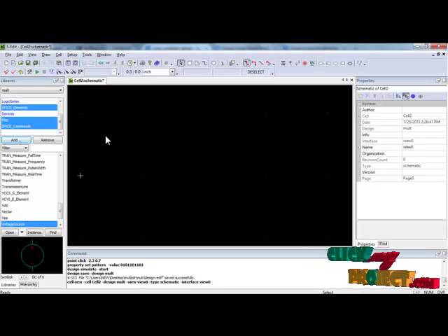After we design in S-Edit, while simulating, the circuit design passes through T-Spice, which we can understand through the netlist generated as SPICE code. Finally, while simulating, the timing diagrams appear in W-Edit. Hence, for our CMOS based designs, we mostly use these edit tools: S-Edit, L-Edit, W-Edit and T-Spice.